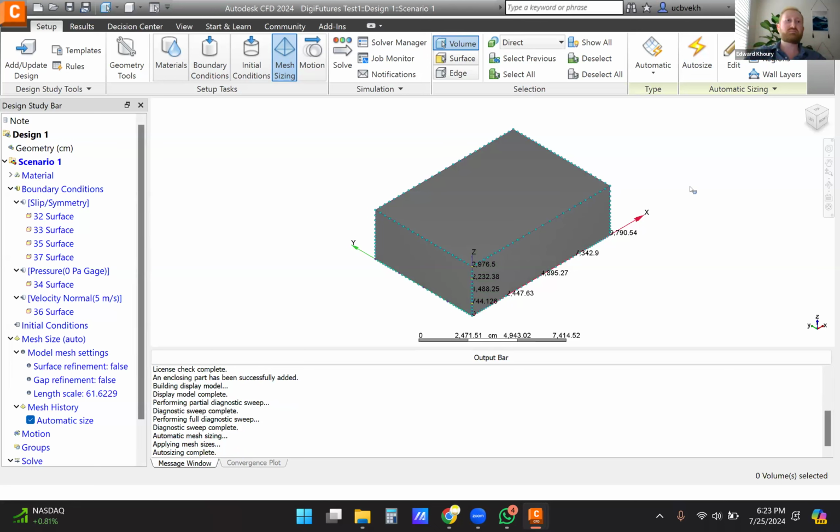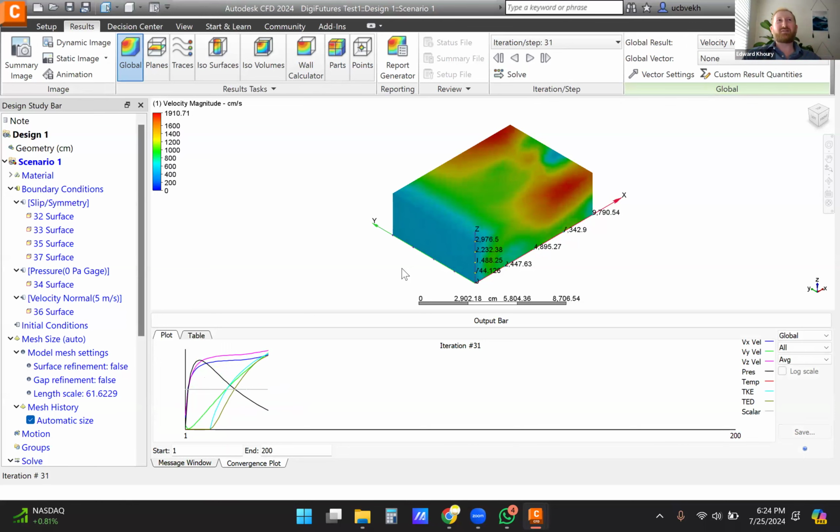Sometimes you get error messages for whatever reason. Maybe there was something not selected right, an unassigned material. Sometimes the model's too complex and it can't handle it. There's lots of interesting ways that CFD figures out how to crash. Like even just putting the boundary box around the object from CFD, it'll just crash. And so you might have to either retry, because it maybe just ran out of data, or try a different method like making the boundary box in CFD.